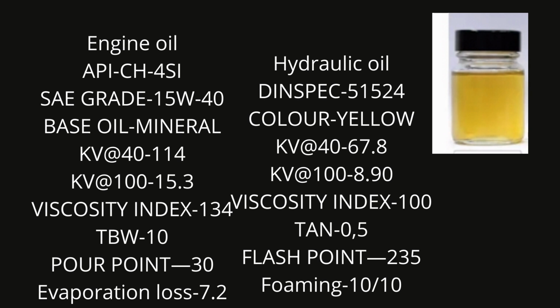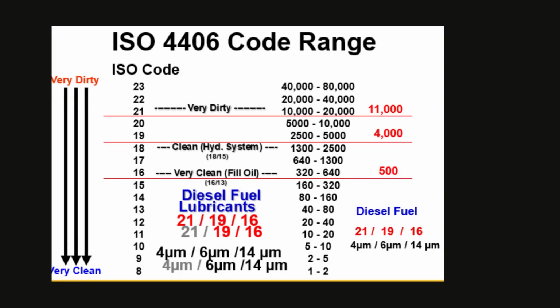Then some of the basic properties of engine oil: API CH4/SI grade, 15W40, then viscosity index. These are some basic values derived from the OEM oil companies. This is the ISO coding chart for cleanliness of the lubricants, diesel fuel lubricants.